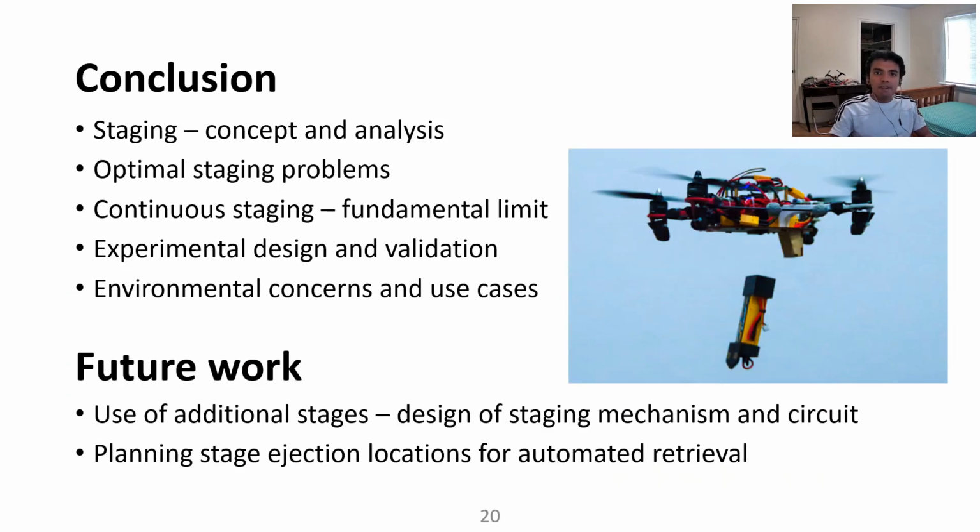To conclude, we presented the concept of staging, where we use the energy source in multiple stages and eject each stage after consumption. We also carried out an analysis to predict the flight times for a multi-stage vehicle with given energy storage parameters. We then considered and solved two optimal staging problems to maximize the flight time, namely the optimal order of staging and optimal mass partitioning.